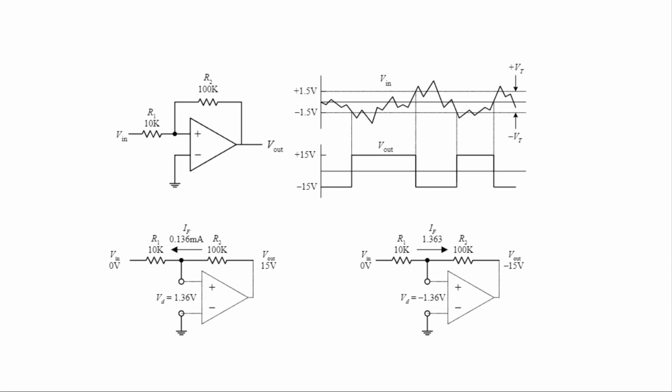The non-inverting input, V positive, term changes to F of V out, just like the negative input turned to F of V out previously. So you get V out equals the gain times, in parentheses, F of V out minus V negative. This is similar to the equation for negative feedback.